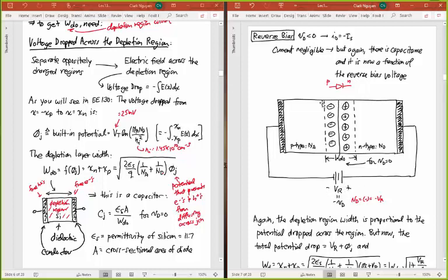So think about this. This is the depletion region with 0 volts across it. That's WD naught that I'm already indicating right here. Right? So that's WD naught, and that's the case with V sub D equal to 0 volts. Now what I'm doing is adding a V sub R to that. So I'm really subtracting V sub R from that V sub D, but I'm putting a reverse bias voltage on this, where the negative is on the P side, the positive on the N side.